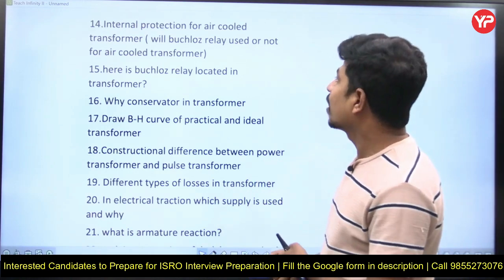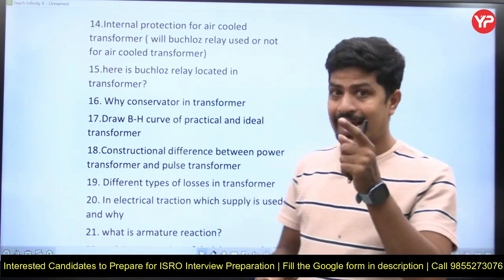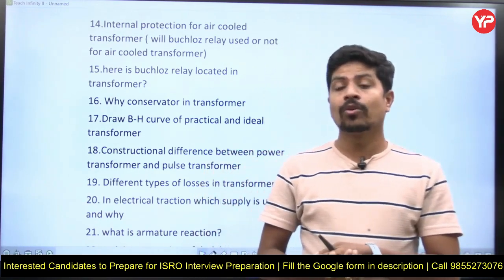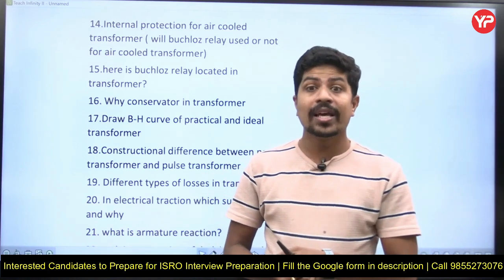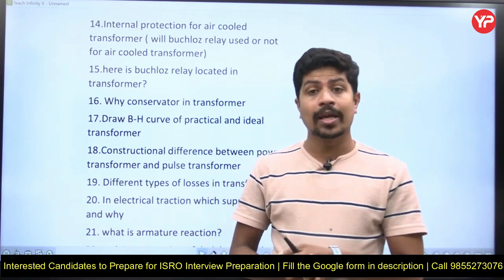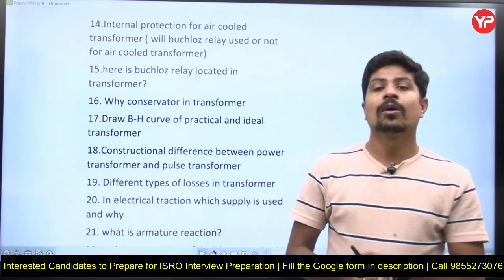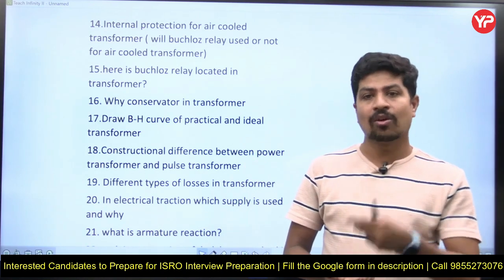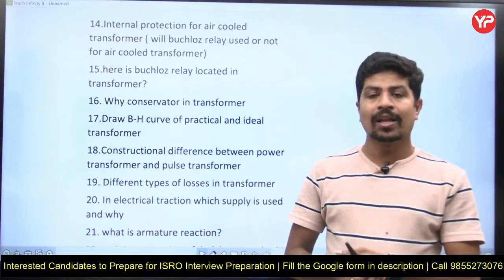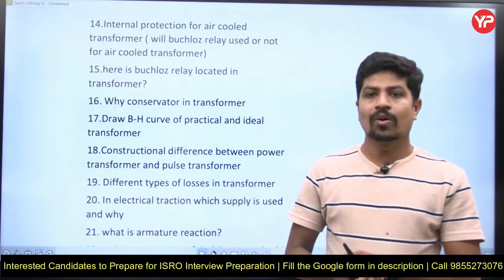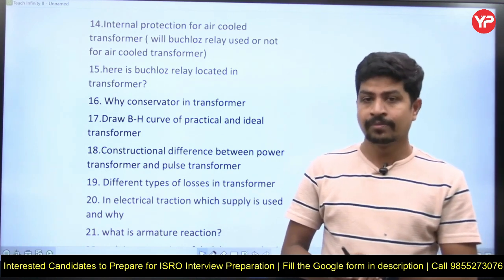Next, internal protection of air cooled transformer. Yes, he is saying it is not oil cooled, it is air cooled. Whether Buchholz relay can be used or not in an air cooled transformer. Buchholz relay cannot be used. Buchholz relay is the relay which is going to recognize the oil level in the transformer. If the oil level reduces, then it is going to raise an alarm. Okay, it is not going to give any trip signal to the circuit breaker, right?